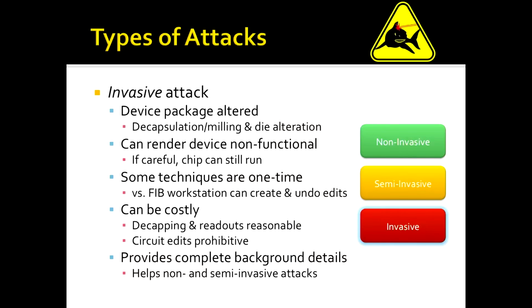Whereas the decapsulation and the readouts of the imaging of the chip can be somewhat reasonable, actually being able to edit the chip can be very prohibitive, depending on if you have access to the equipment or an hourly rate to get on the equipment. And then finally, this class of attack will pretty much provide you with complete background details.